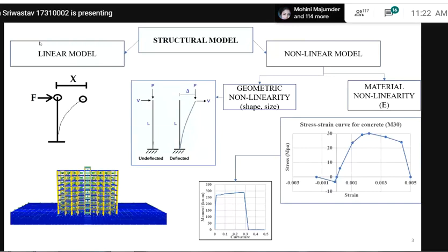If we know the forces coming into this building, we can create a stiffness matrix for the structure. We do not know how to create it at this time. So if we know the forces coming into the structure and the stiffness matrix, we can easily know the deflection at the various points. Using that, we can design the structure.